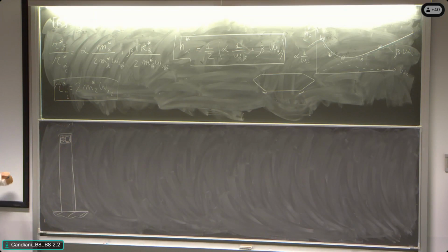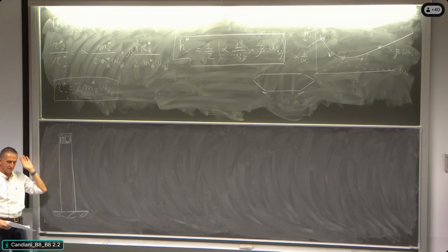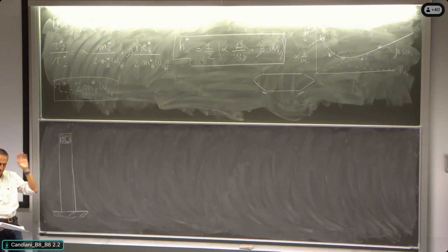It means that it is oscillating intrinsically at the same frequency of the building, so that when the building is moving at the frequency that we want to protect, this motion that is given to the constraint of the mass is exciting the resonance of the mass.